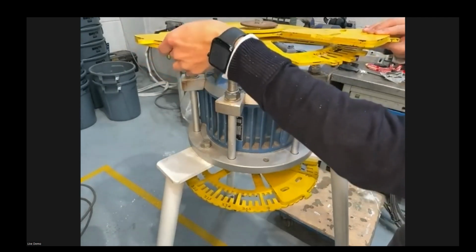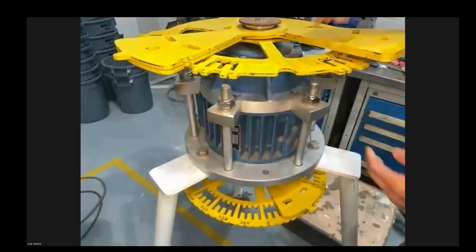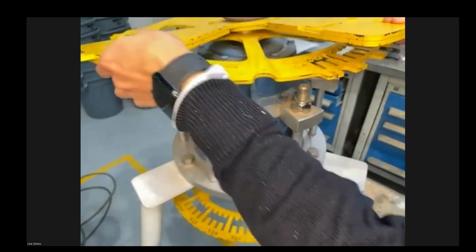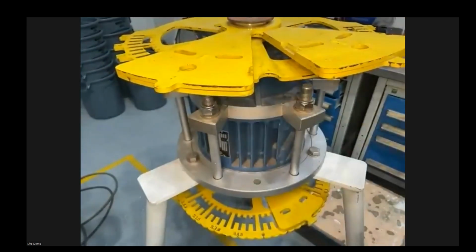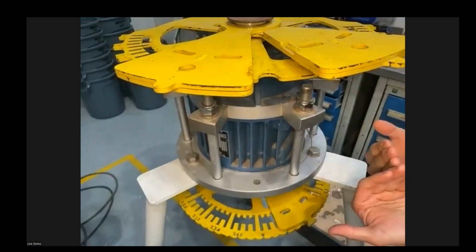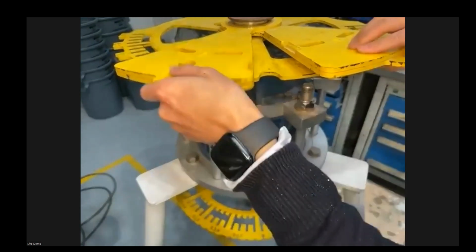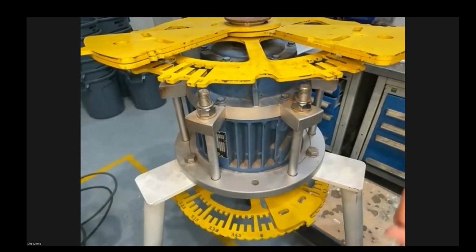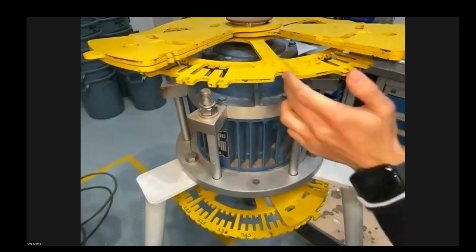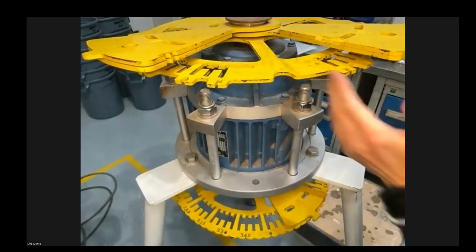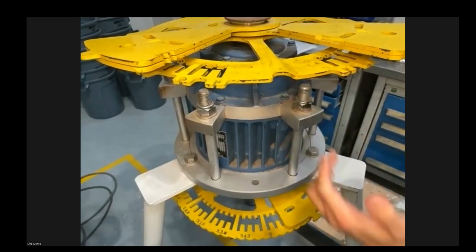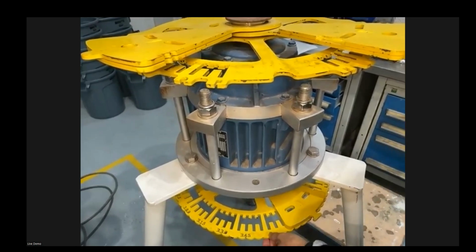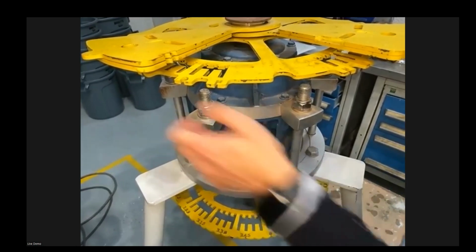You have wings on each wheel. You can understand that if you put the wings closer to each other, you have more centrifugal force, so we have more force. If you put them apart, they will have less force. The top weight will be the reference, so always 0 degrees, and what we call the lead angle will be the angle we have on the bottom wheel.